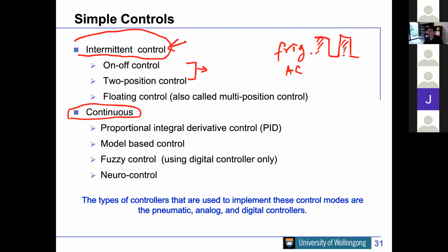If you adjust the temperature of your fridge to be higher or lower, what the controller does is switch between this time, T on and T off. I make this time ratio slightly different, instead of trying to make the compressor work in different modes, because that's just easier to do.